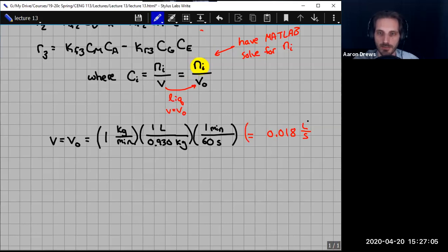But we've got some methanol coming in as well, so we're going to add that methanol to it. The methanol is nice because we already know how much methanol is coming in as a volumetric flow rate, so we don't have to try to adjust that. It's coming in at 500 milliliters per minute, I think is the number that I had. Yeah, 500 milliliters per minute. Actually, let's convert that real quick: 0.5 liters per minute, and every 1 minute is 60 seconds.